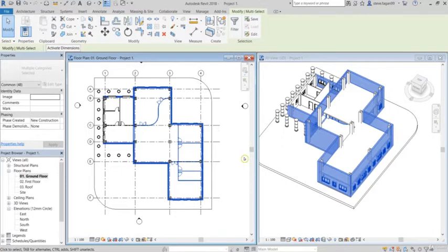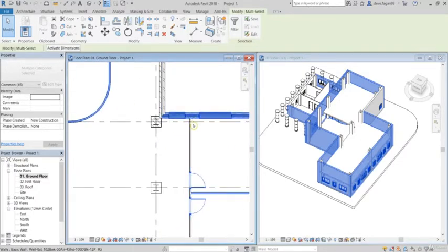But as we've selected walls, both the external and the internal fall under the same category, so they're both highlighted. We don't want our external walls to be copied up because then they'll be duplicated over each other. So we need to deselect those external walls. So to deselect a component, hold down the Shift key. When you hold down the Shift key, you'll see a little negative symbol appears on my cursor. And we can then select the external walls and what we don't want to be selected.